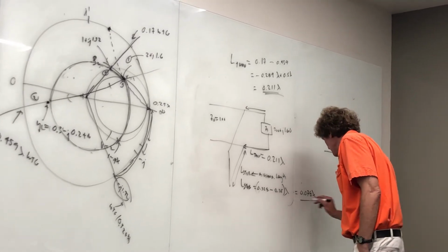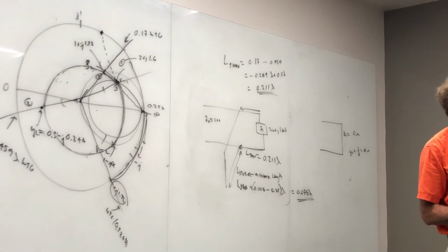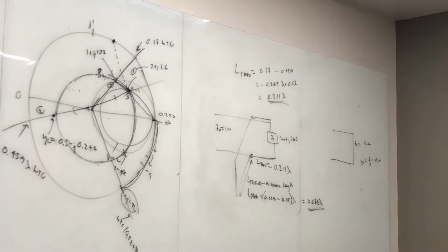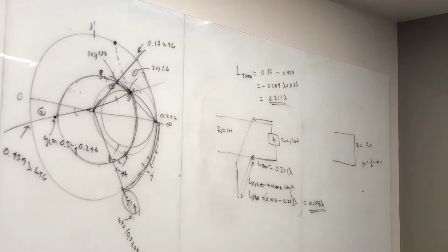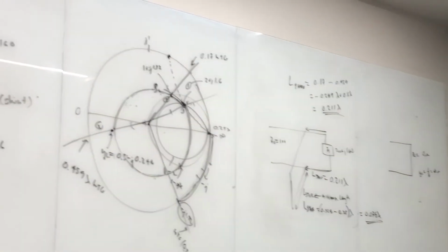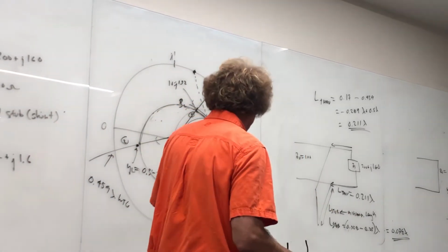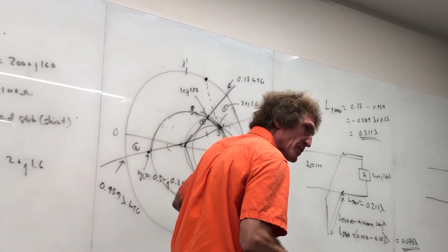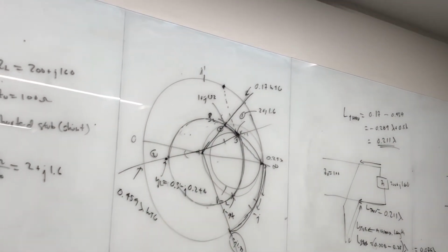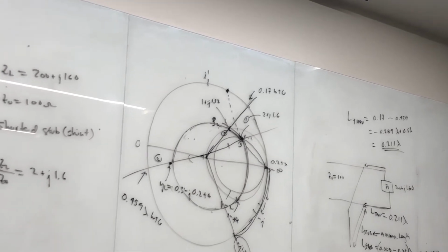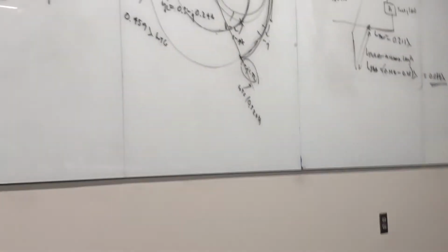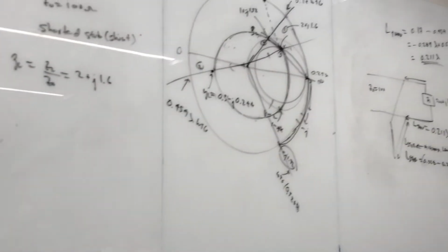0.078 lambda. Does anything trouble you about that? Okay, so are we looking for where the 1.32 is on the outside, or where it intersects the arcs? You're looking at, here, let me show you actually. You're looking for where the intersection is on this rim, where it's minus j 1.32. So you're just looking for where that value is on the outer ring. That's going to be the intersection, then you draw a straight line through it. So minus j 1.32 is right about here.